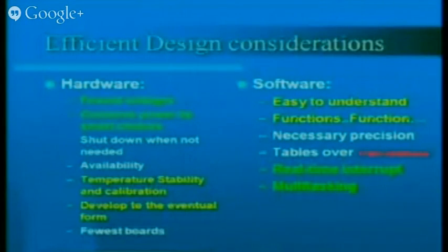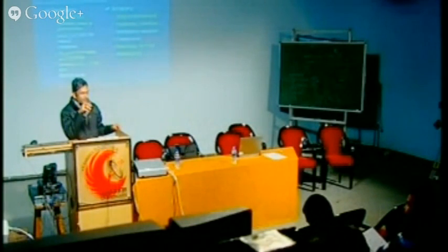Okay. So, lowest voltage is one of the considerations that we should make, and conserve the power by small measures. That on-off thing you can do, that is a software thing. And obviously, you can select the ICs which consume less power. So it's a consideration, because for the same functionality, like a switching matrix, the same switching can consume less power or high power.